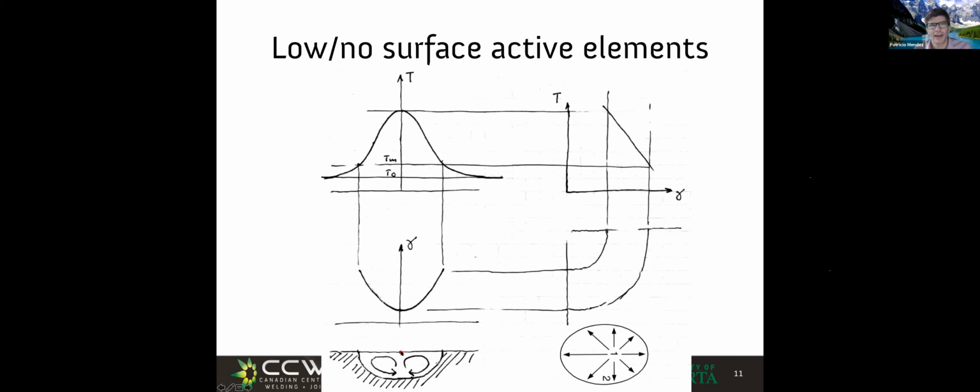So the net effect is that on the surface, I have a force that pushes the surface of the liquid outwards in this form that is illustrated here. The flow goes out. Now, if the heat comes here on the surface, I want to ask you, do you think this sense of recirculation that is towards the outside would give us higher or lower penetration?